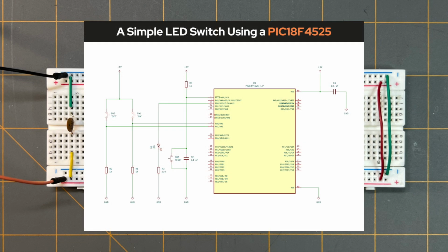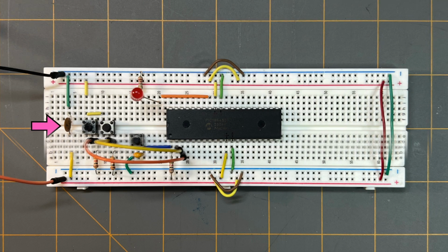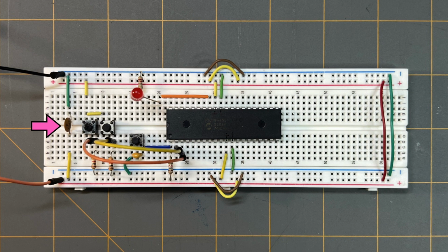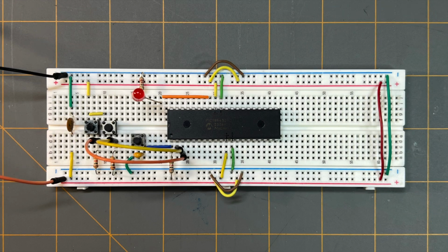Pins 12 and 31 of the PIC microcontroller are its VSS pins. Both VSS pins of the PIC will be tied to ground. Both VDD pins of the PIC will be tied to the plus 5 volt supply. A 0.1 microfarad ceramic capacitor will be tied across this connection and ground to help stabilize this voltage for the PIC.